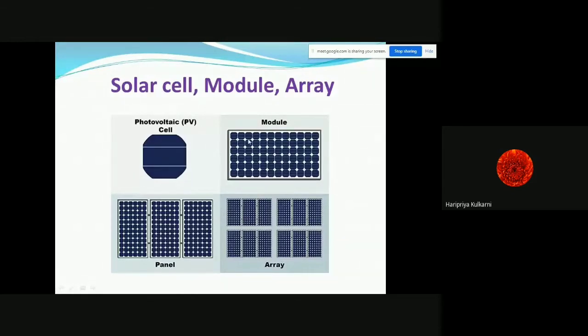First, series connections are made to increase the voltage level. Suppose each is of 2 volt, then it will be 24 volt, right? 12 cells are there, they are connected in series, so it will be additive. So 12 twos are 24. So one series will give us 24 volt, and let us say it is giving us 1 milliampere, then with 6 parallel paths it will give us 6 milliampere. So it is 24 volt, 6 milliampere. I am just taking an example.